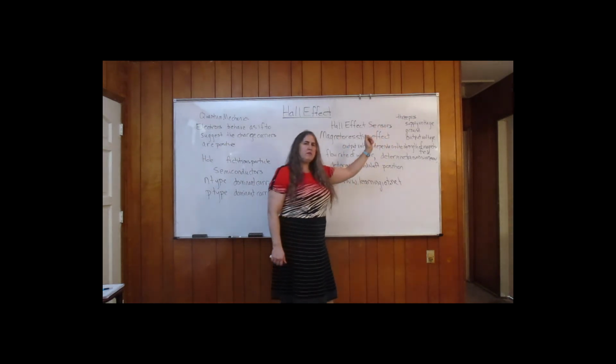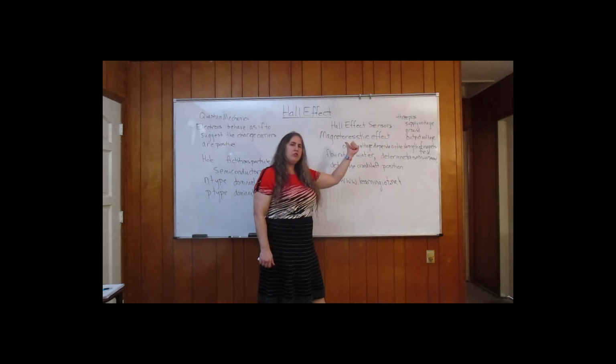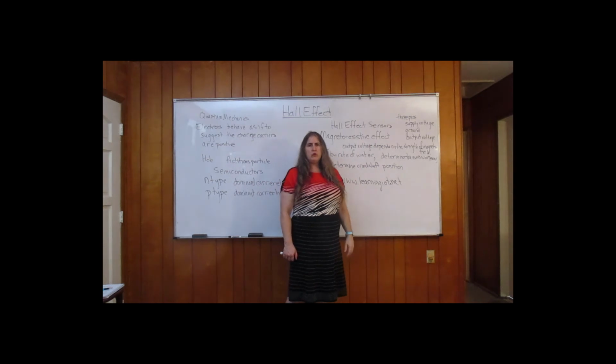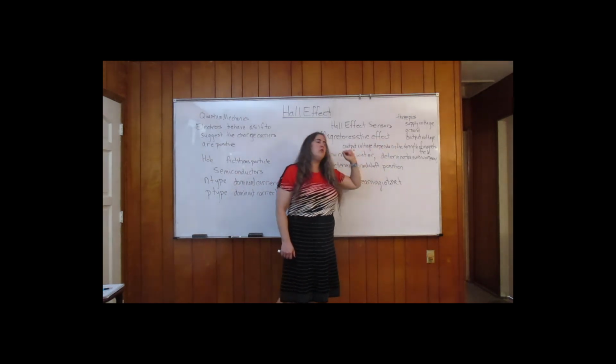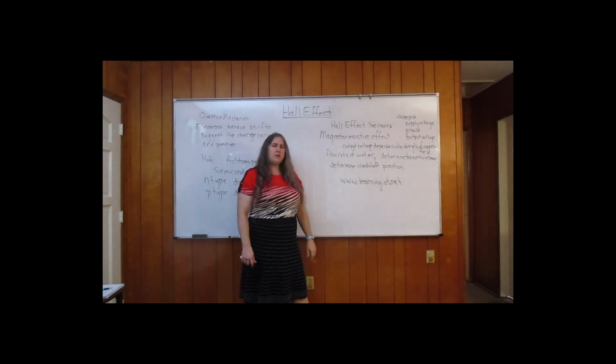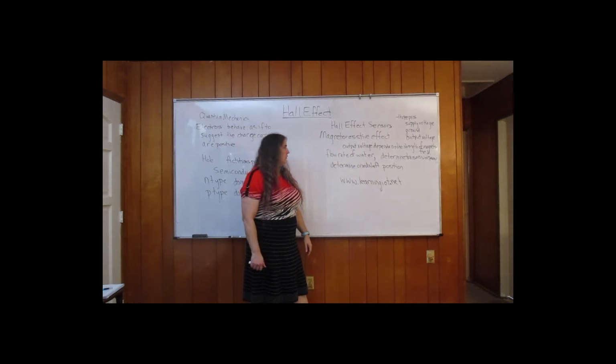And they have 3 pins. There's one pin for the supply voltage, usually taking between 3 volts and 6 volts in a lot of cases. There's a grounding pin, and there's the output voltage. It's the output voltage that depends on the strength of the magnetic field.